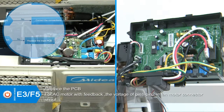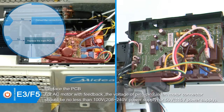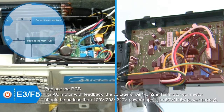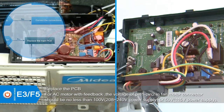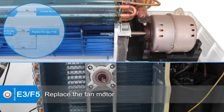Examination for main PCB board. AC motor with feedback. Turn the power on and set the unit as running in high-speed mode. 15 seconds later, measure the voltage of pin 1 to pin 2 in the fan motor connector. If the value of the voltage is lower than 100 volts for a 208 to 240 volts power supply, or 50 volts for a 115 volts power supply, the PCB must have problems and needs to be replaced. If the value of the voltage is normal, the fan motor needs to be replaced. If the error still exists, replace the main PCB.